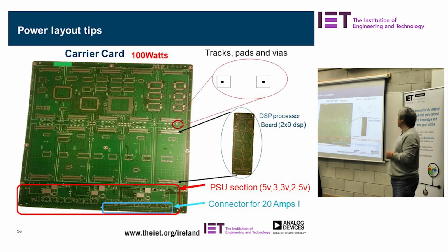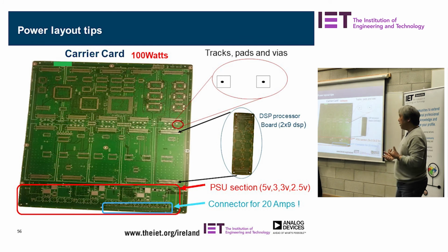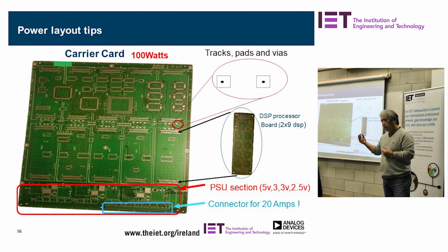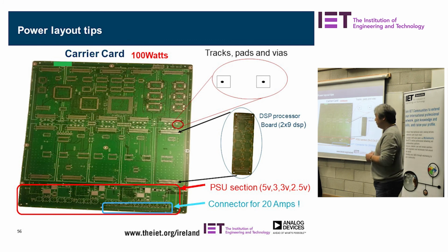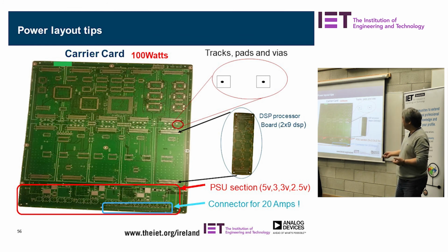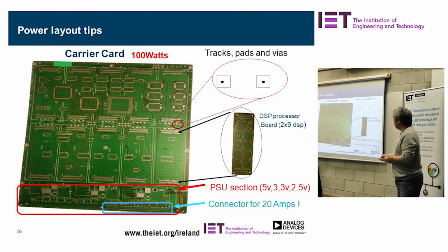Okay. So here's things that, when you come to design, like I said, it's all very good on paper. So always follow through with your layout guys and tell them what to do. For instance, this board I designed, I gave it to the layout guy to lay it out. I found so many flaws, and I had to teach him, even though he's done layout for 20 years, because this one takes about 20 amps on this supply. So we look at some of the power issues that you need to follow through and be aware of.